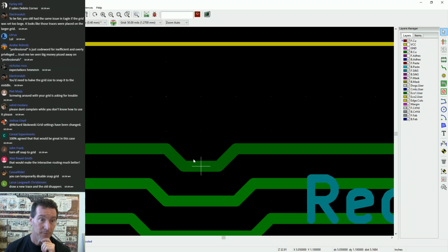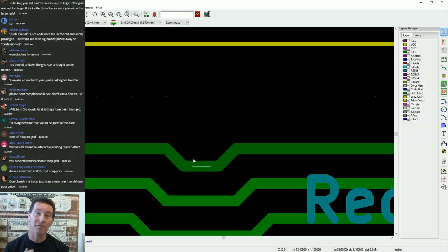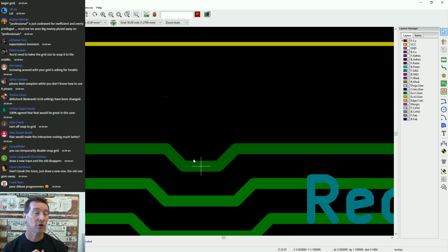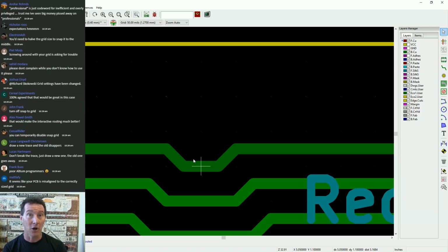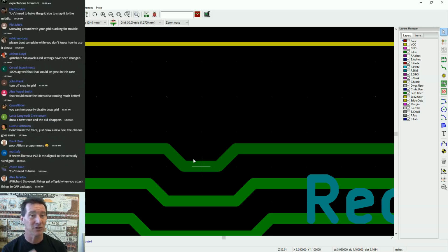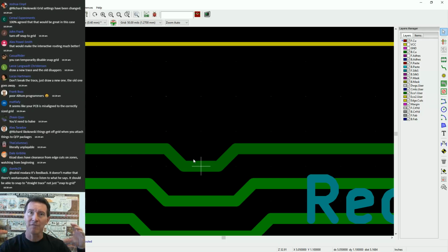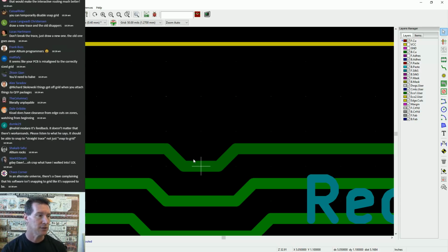Richard asks a good question. Why did a professional PCB designer put traces off grid? Well, I didn't design this board, but there are many reasons why you would do that. When you're designing a board, especially a complex one, you are changing your snap grids and visual grids all the time for various reasons that I won't go into. Like, you're mixing imperial and metric components, surface mount and through hole. You're doing all sorts of other stuff. You're working on high density stuff versus larger stuff.